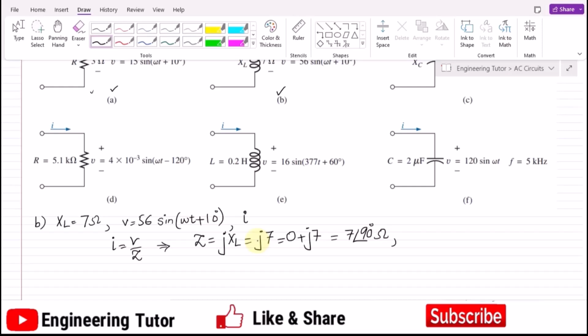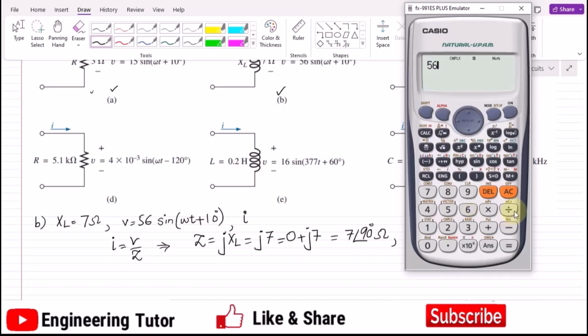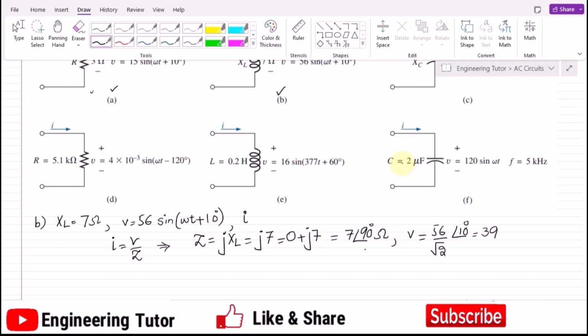Similarly, in order to find the voltage, we have this peak value. In order to convert it into the RMS value, we have to divide this 56 over the square root of 2, and the angle is already given here, and that is 10 degrees. So 56 divided by square root of 2 is 39.5, and the angle with it is 10 degrees.